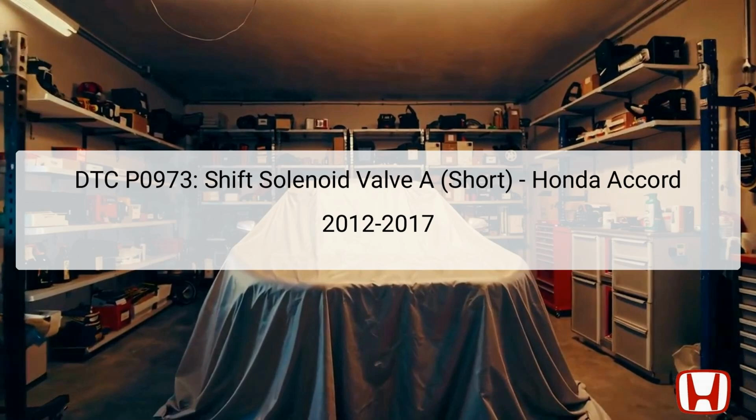When a fault is detected in this component, the vehicle is unable to shift into the second or fifth gears due to a fail-safe mode activated to protect the transmission from further damage. To begin troubleshooting, it is essential to capture all freeze frame data and onboard snapshots using the HDS or Honda Diagnostic system before proceeding with further steps. This diagnostic code is purely electrical, indicating that mechanical issues with the transmission are not the cause.